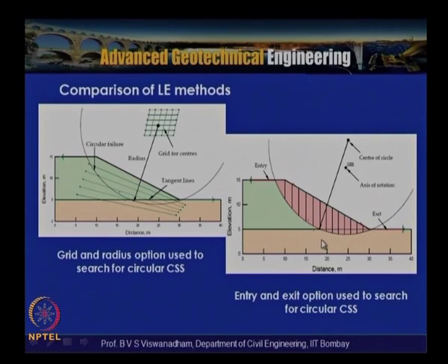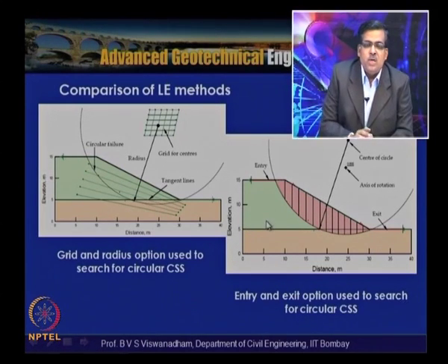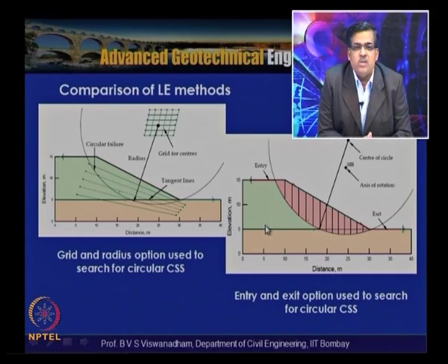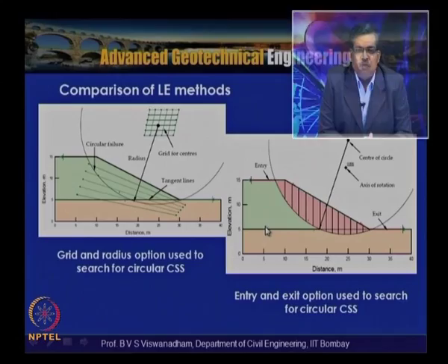So we know that whenever there is a soft soil, there is a tendency for the circle to draw down towards the base of the slope. But if there is a hard stratum, and the slope is constructed above the ground surface or above the hard stratum, then the slope fails within the toe or the slope surface.